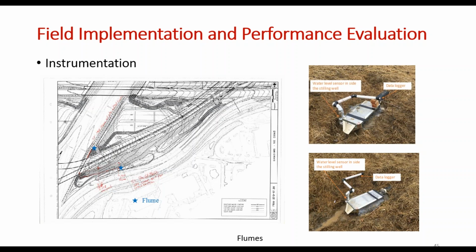So here are the installed outlets. Actually, the change of location affected the way that we look at the data, because the distance from the wall is different. So you may have loss of water along the way, and the new location on the road has a very small grade. Okay, so it's less steep, so if there is water, it will flow slower.